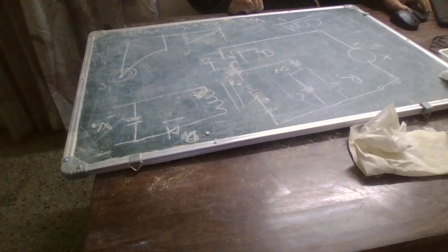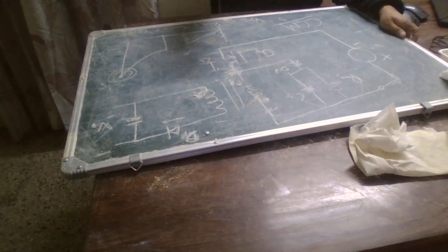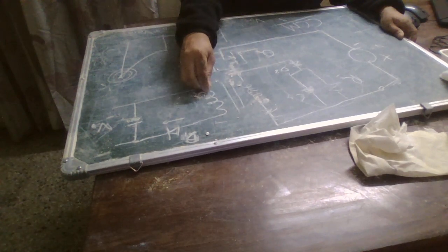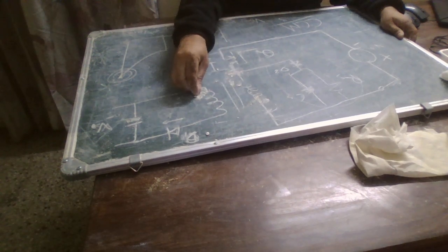Here one more thing is that we take an air gap flyback transformer, because we want to reduce the chances of magnetic saturation. We do not want the flyback transformer to get saturated, and it will saturate very easily because of imbalance in the flux changes during the T on and the T off cycle.